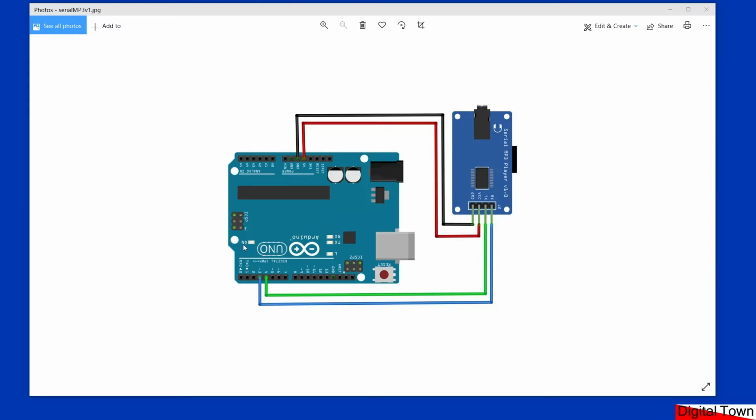Yes, one other thing. When you are putting your files onto the SD card, one of the things I've noticed with this module, and I've had the same with the DF Mini player, is that they don't seem to be able to cope very well with any fragmentation of the files. It's almost as if they're pushing themselves to the limit. So what I tend to do is format the entire card and then put all of my files on in one go so that there is no fragmentation in there.